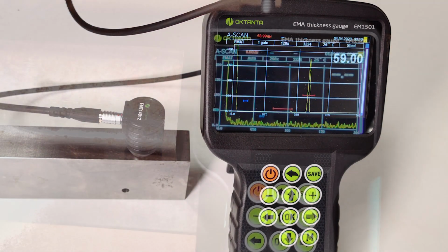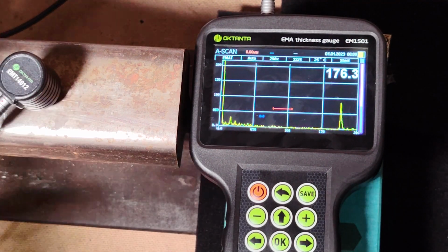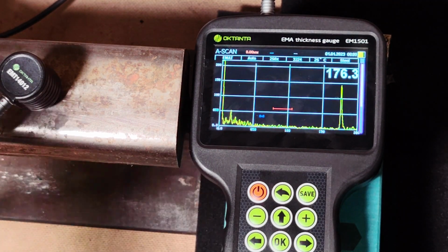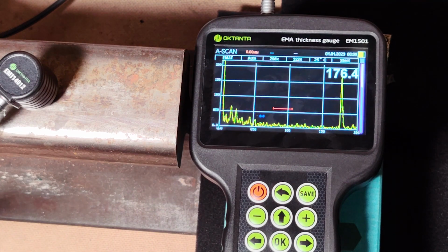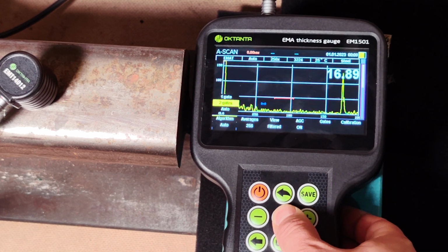This method of taking into account only certain selected echo signals is well suited for inspection of thick but heavily corroded test objects, as well as products made of cast iron or other cast products, since when testing such products, there are parasitic interfering echo signals due to the coarse grain structure.